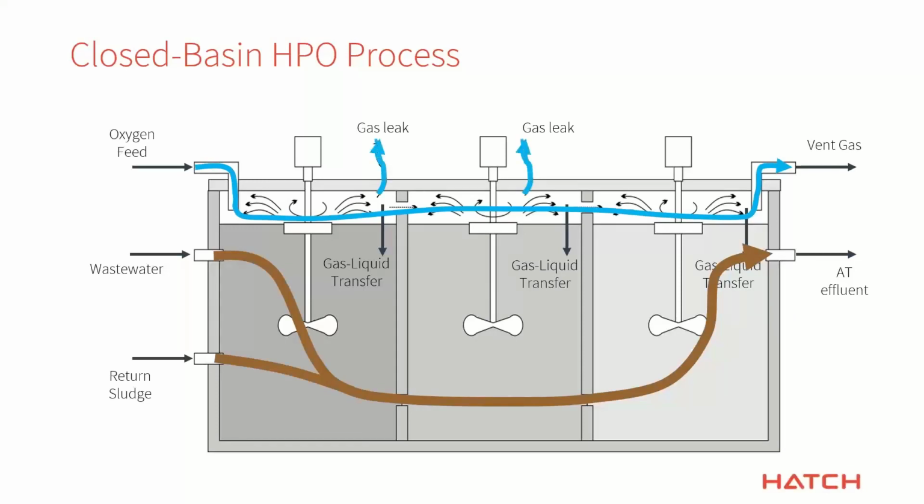Now, some of these systems do potentially leak. I've modeled quite a few of them over my career, and almost all of them, in discussions with the operators, are never perfectly sealed over time. So it's good to be able to include that part in the model so that you can mass balance your oxygen appropriately.